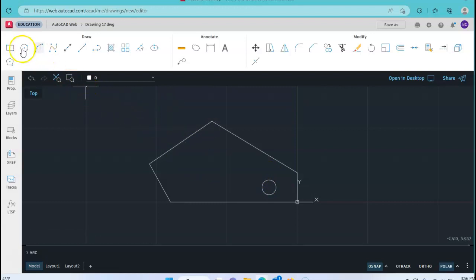Let's do the same thing. I can go back up here, click my circle tool again. Looking at my dimensions on here, I see that the center point here in the X is going to be -3.5, comma, +1 in the Y, enter, and in this case my diameter is 1, so for my radius, I am just going to save myself a keystroke and go 0.5 on the radius, which will give me a 1 inch diameter. And this drawing is now done as well. So I've completed everything there.